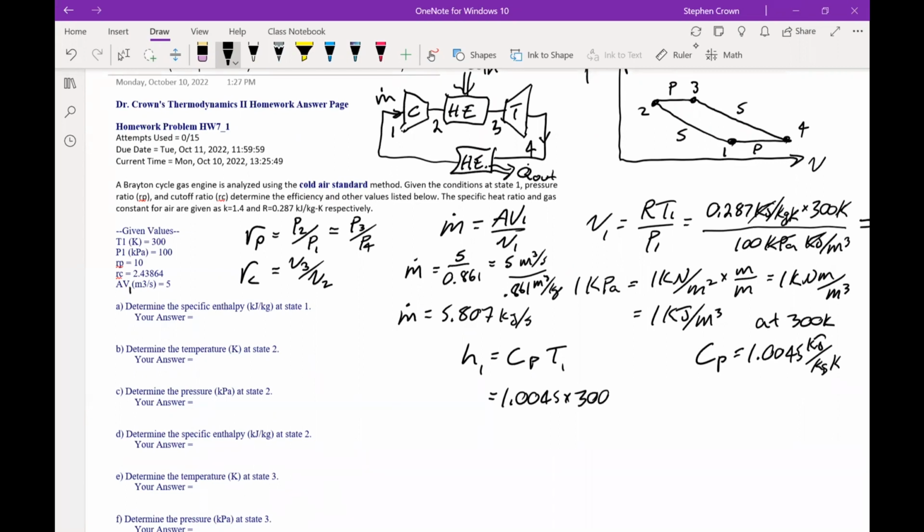Now, normally we would write delta H equals CP delta T. And so any constant could be added to that. We'll always be using differences. So in the homeworks, I always assume that that constant of integration, we had some constant Z, then you could write the enthalpy offset by some constant because we're doing an integration. But in this case, in the homeworks, I use that Z equals 0.